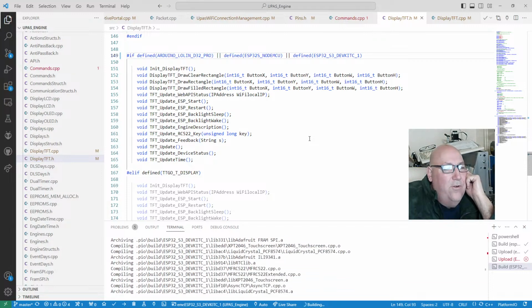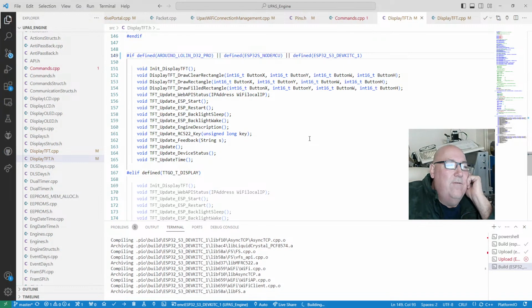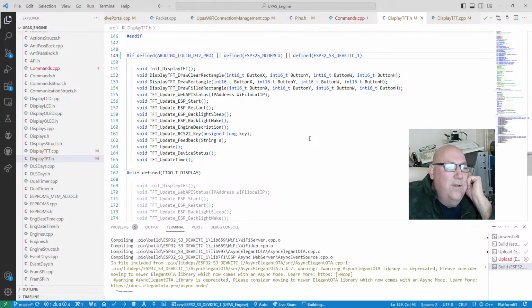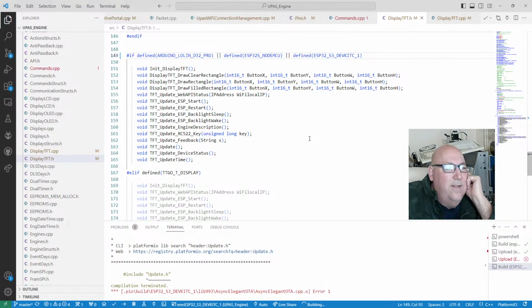But basically, it'll try to load from EEPROM or the equivalent of whatever memory's been allocated as ROM. And if it doesn't find a valid value, I narrow down the bytes that it reads, and if it reads something wild like 255, it'll put a default value in instead.